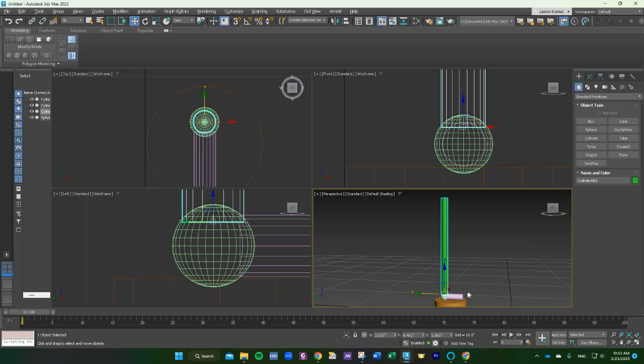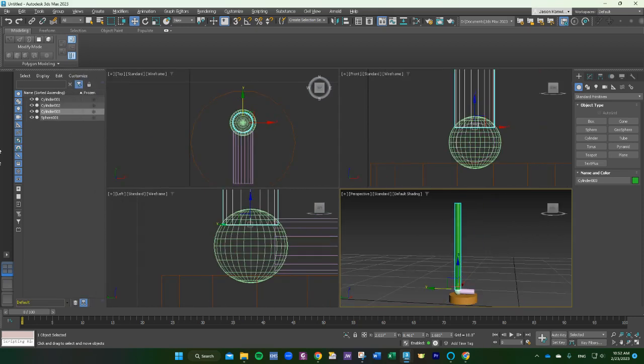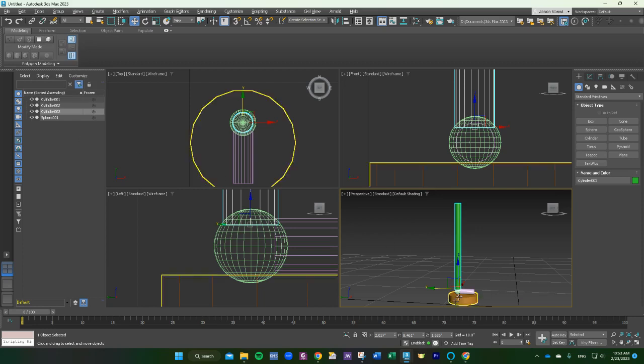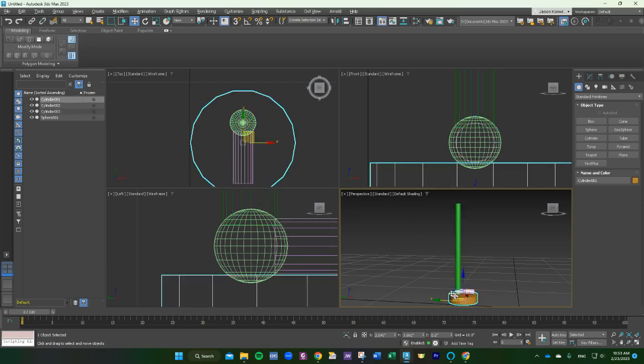So before we get any farther, we're going to model this, and I think we'll leave this off on our first video. We're going to name some of these things in our Scene Explorer here. If yours is not turned on, remember you can find it under Tools, turn on Scene Explorer, pop it up in here, and let's give all the different parts some names. So this first thing, let's call this wall plate.